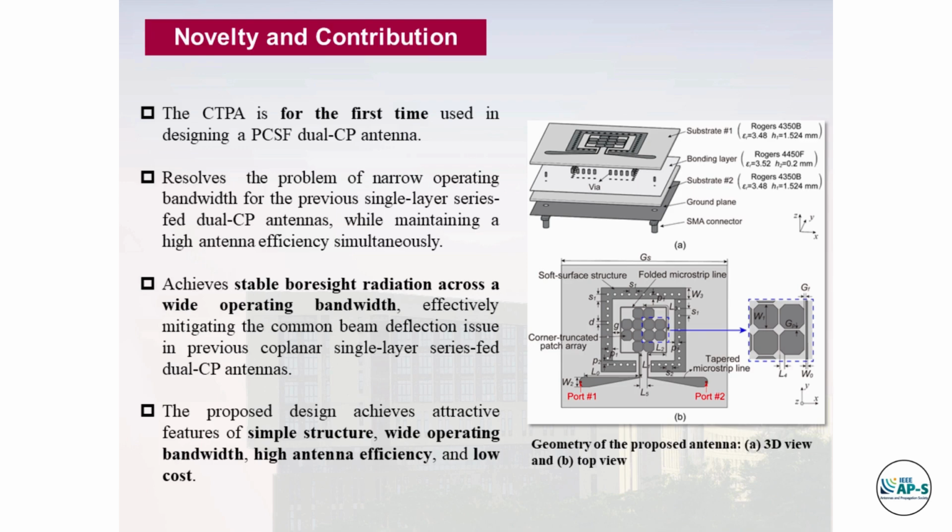Furthermore, the proposed antenna achieves stable boresight radiation across a wide operating bandwidth, effectively mitigating the common beam deflection issue in previous coplanar single-layer series-fed dual CP antennas. Compared with the existing series-fed dual CP designs, the proposed design achieves attractive features of simple structure, wide operating bandwidth, high antenna efficiency, and low cost.